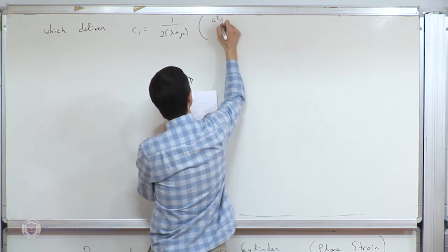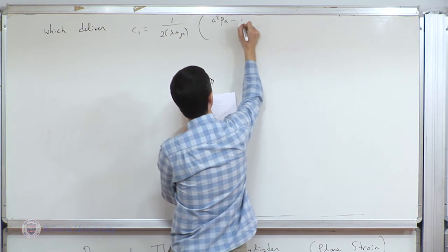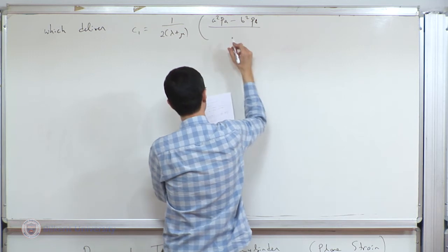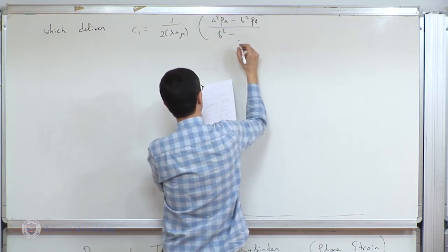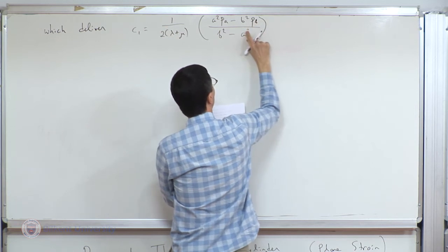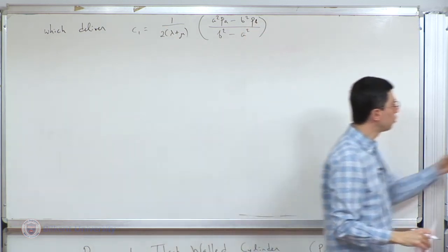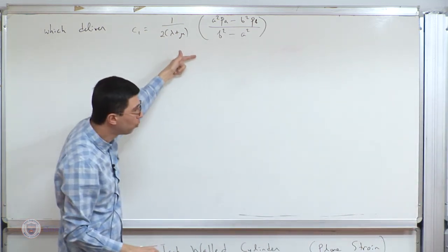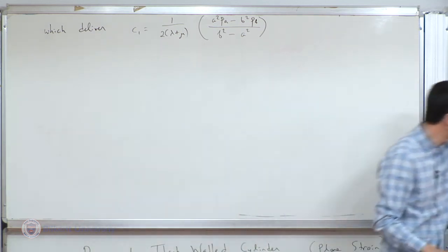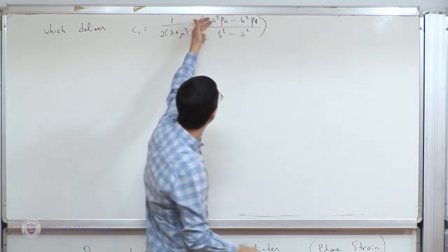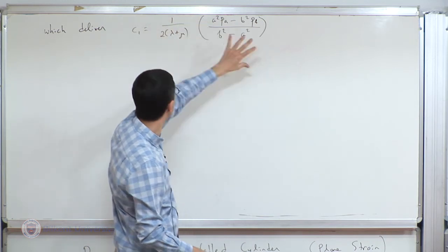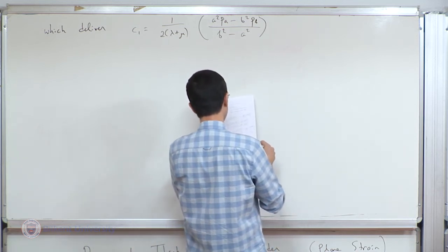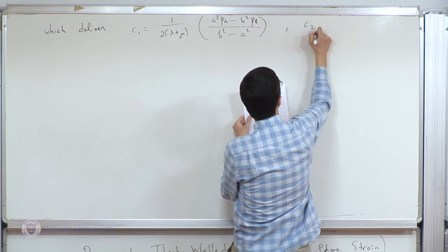So the constants look remarkably simple, of course, because it's a qualitatively similar problem to the sphere with a pressure case. And in that case, the second solution was of the form 1 over r squared. Eventually, that resulted in a 1 over r cubed dependence for the stress. So instead of r squared, we have an r cubed, and instead of square terms, there we had cube terms. But apart from that, these constants, even their forms, are almost the same, almost. And that's C2.